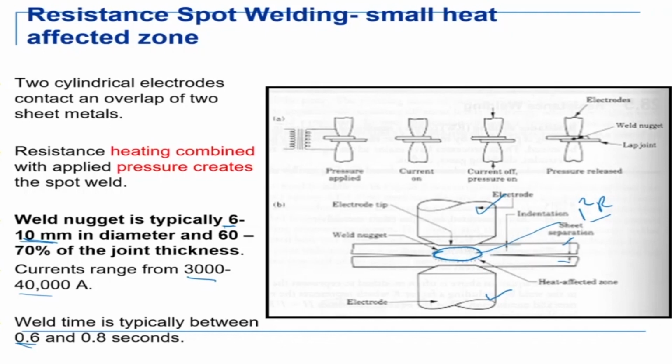Now, what is the advantage of this? The advantage is that it is fast, and many robots can do this very efficiently, but it does not deform the material, because the weld is taking place in between the 2 sheets. So there is no effect on the other side. On a car body, you will not be able to see any deformation because of the weld, but the weld is there. That is where the sheet metal on the surface has been attached to the chassis. So this is what started off the application of robotics in the automobile industry, and even today spot welds are done by robots.